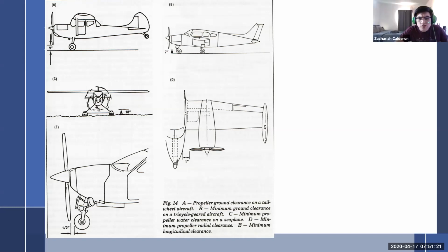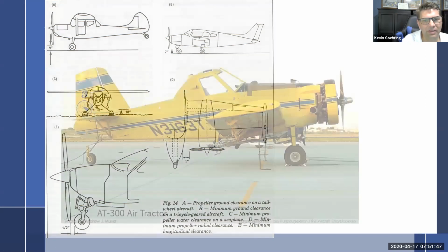Let's see. I have a question about the tail dragger planes again. Yep. So is the rear wheel stationary, or is it like a shopping cart wheel? It's like a shopping cart wheel that is attached to the rudder, but it's not hard attached. You have springs that attach to the tail wheel that attach to the rudder. So I think the next slide, let me see. Next slide, I might have something on there.